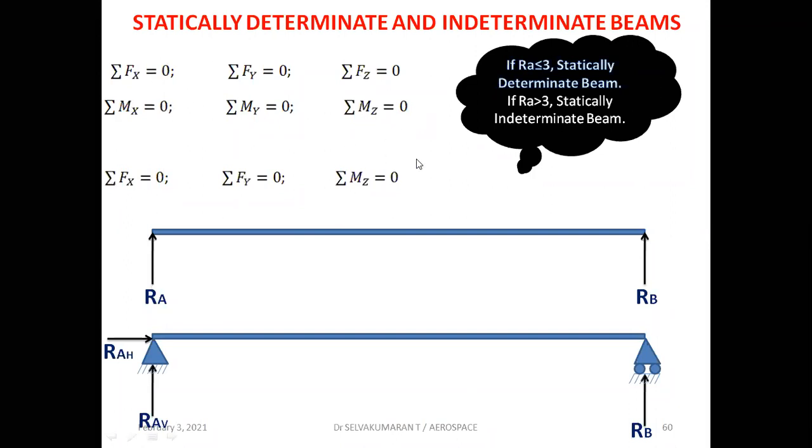But in solid mechanics or strength of materials, we'll be using sigma Fx equals 0, sigma Fy equals 0, sigma Mz equals 0. If you just imagine that this diagram is on a paper having x-axis and y-axis, the z-axis will be perpendicular to this plane or paper. That's why it is written moment about the z-axis. If you're taking moment about A, sigma Mz suffix A is the moment about the z-axis only, but we are taking the moment with respect to a reference point A.